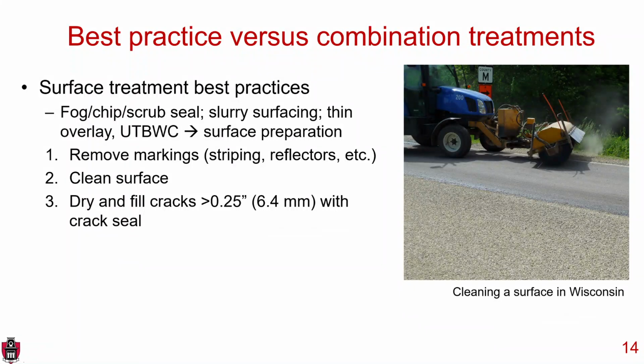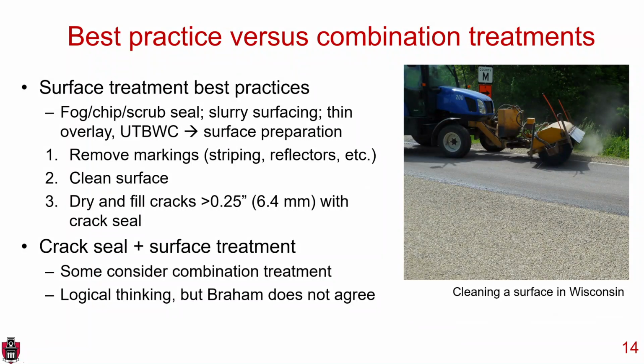Now, again, you can have a robust conversation about whether or not having a crack seal plus any of these surface treatments is a combination treatment. And I've had conversations with people who believe they are combination treatments. I respectfully disagree with them because I think that if you are applying any surface treatments as part of the best practices, you should make sure your cracks are sealed. Therefore, this is not a combination treatment. It's simply applying the best practices for that surface treatment.